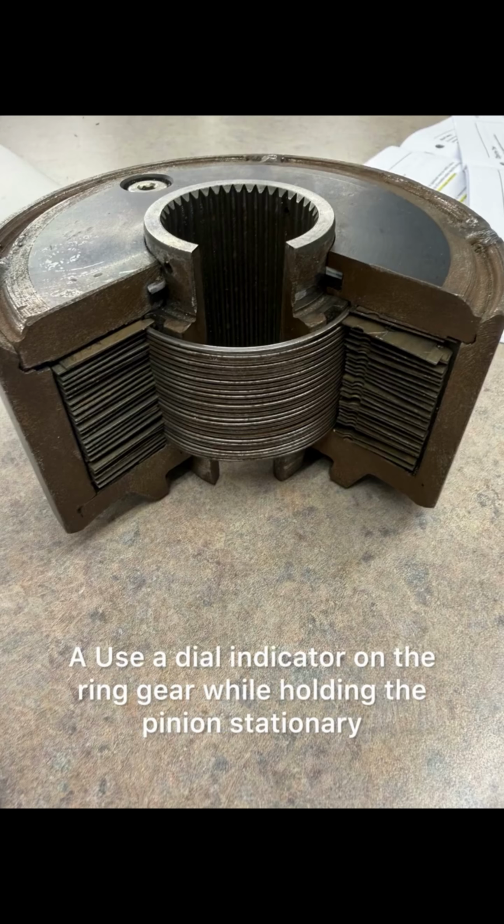22. How do you test if a differential is open or locked? A. Lift both wheels and rotate one wheel; opposite direction means open. 23. What does burnt smelling differential fluid indicate? A. Overheating from low level, wrong oil, or excessive load. 24. Why would noise get worse after a differential rebuild? A. Incorrect backlash, pinion depth, or bearing preload.